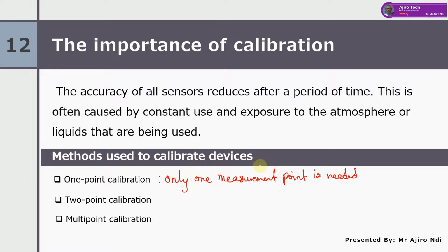Now, the sensor being calibrated is different to a standardized sensor by +1 at the lower end and -5 at the higher end. The calibration cannot be carried out by just adding an offset value in this case, since the offsets are different for every pH value. There is, however, a linear relationship between the two, and to calibrate the sensor, the algorithm will need to multiply each reading by 2 and subtract 3.